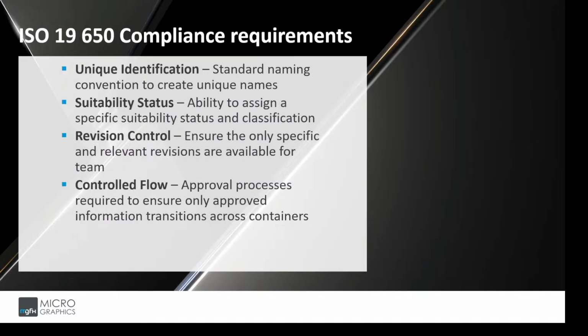Okay. Looking at the ISO 19650 compliance requirements, to support the structured workflow, a technology platform must meet several key requirements to be considered an ISO 19650 compliant common data environment. These include the following: a unique and standard identification for every information container based on an agreed and documented naming convention. Then it should have the ability to assign attributes for status, suitability, revision, and classification.